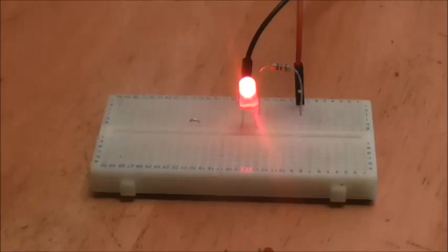So, the red LED. Now, when we looked at the barrier and the Schottky and the Zener diodes, what we found was that we had a PN junction. And we doped the PN junctions with things like boron, antimony, phosphorus, and made them do the conduction like that. With an LED, we use slightly more exotic materials. We still have a PN junction, it still works as a normal diode, but the materials are different.